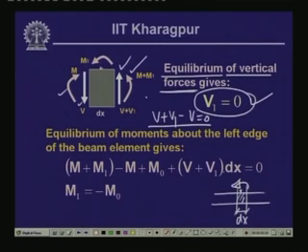So, along the length of the beam, whenever we come across a concentrated moment at a particular point, and if we are computing the shear force on the left of that concentrated moment and the right of the concentrated moment, we will find that there is no change in the shear force. Now, what happens to the bending moment?